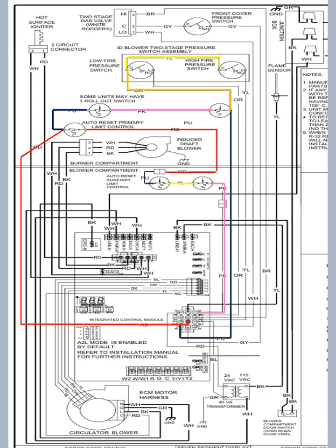This proves that the pressure switches are open because the voltage doesn't travel back on the outlet orange wire to pin 5 of the 12-pin connector, and also the yellow wire that goes back to the 12-pin connector isn't going back either. But if it was, like on our first stage, you see that goes down to the 5 pin. That would show that pressure switch is stuck, and you'd get an error code that the pressure switch is stuck closed.